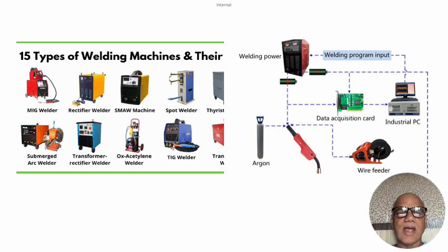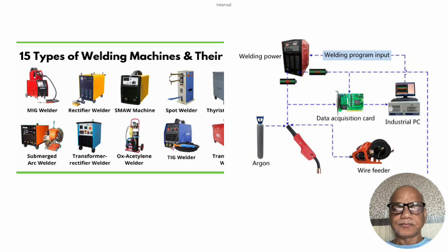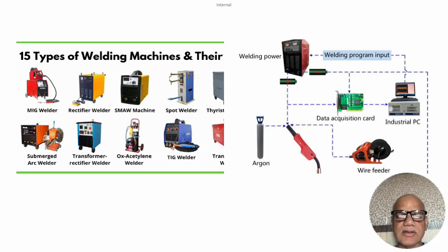And later on, as we found that instead of AC, DC is a better source, we moved from transformer to thyristorized machines. These are once again very simple rectification using diodes or thyristors, converting three-phase AC into three-phase DC and superimposing that to get better ripple factors. Less ripple factor in a welding machine gives a pure DC and gives lots of advantages.